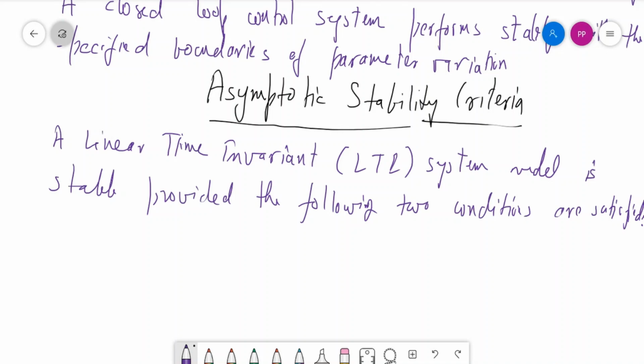Say I am giving a bounded input, say a magnitude of 2 volt and 2 hertz, and the output goes tremendously high, 200 times, then we say that the system is going out of bound. So for the bounded input there should be bounded output.